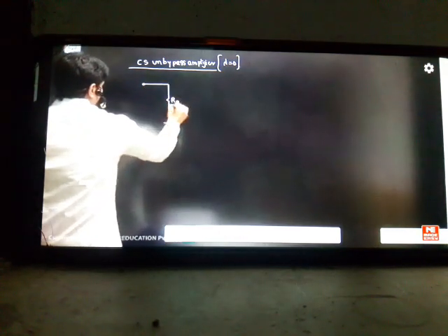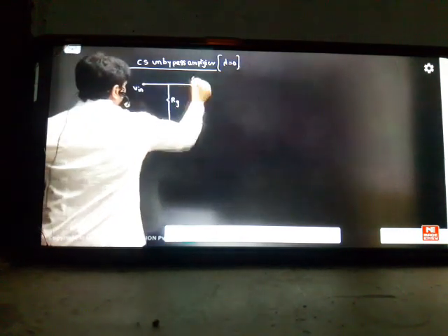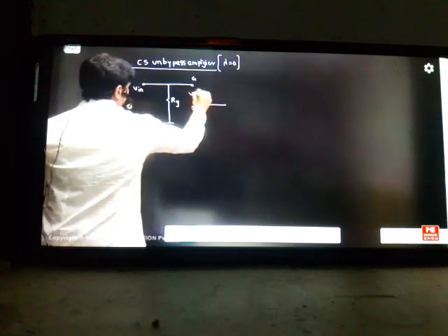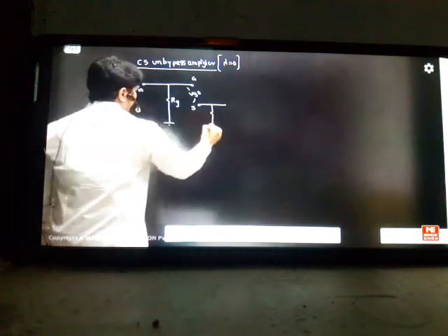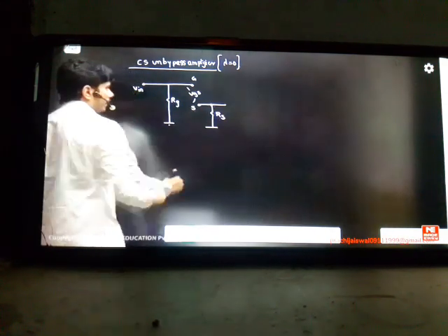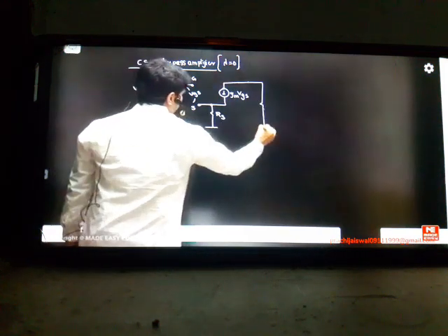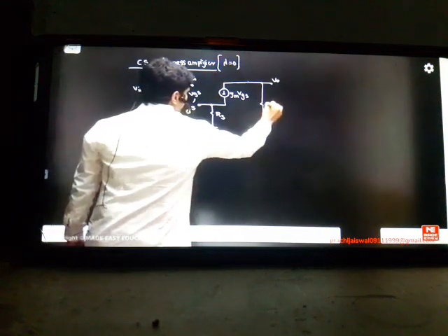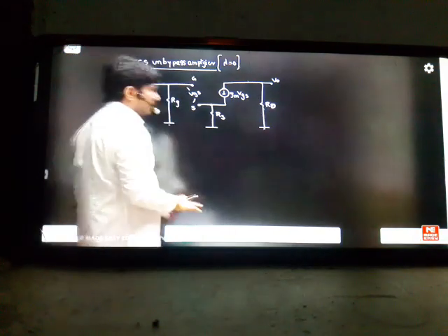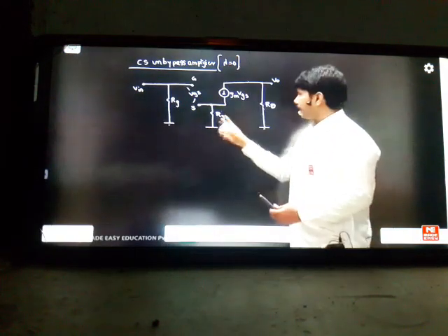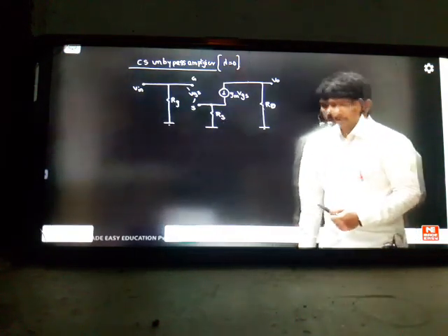This is RG. This is VIN. Next is gate open. Source, VGS. Up to here we have VGS, but after VGS we have RS from the source. Next we have the current source, GM into VGS. And finally, we have the RD. So maybe the model looks like this. Everything is the same. Input is open, but we got some extra RS on the board. This is the diagram. First, you have to practice. Let us see the formulas now, how to write them.